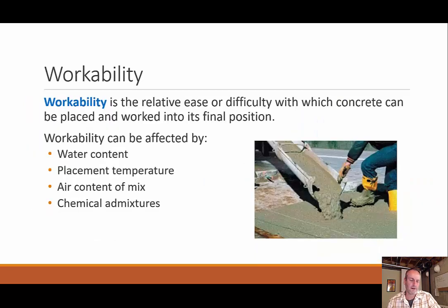We're also concerned with workability. So how easy is it to be put into the place where you want it to be? And just like before, if you look at all the ingredients, it affects workability. Water, actually, if you add more water, it helps with the workability, makes it easier to flow around and get to where you need it to be. But like we said earlier, it decreases the strength.